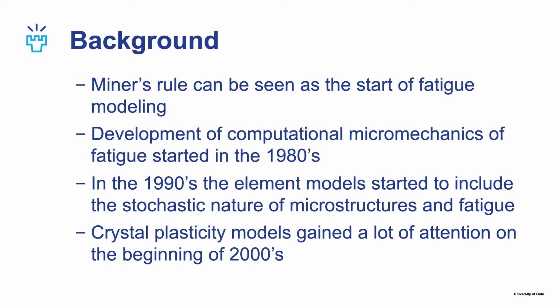Miner's rule allows the prediction of the remaining life of the component based on the damage accumulated in the previous cycles. After Miner's rule, there have been a lot of these equation type empirical models, probably one of the most notable being the Chaboche and Lemaitre model, developed in the 1980s.